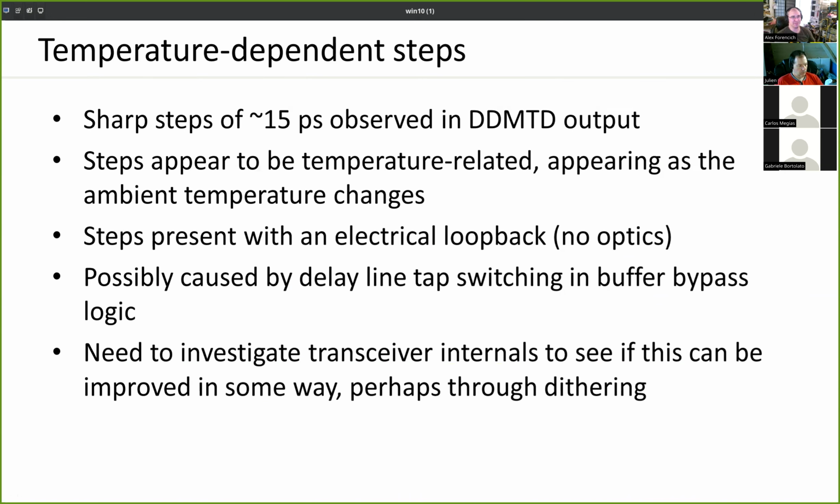I'm not sure how much I've discussed this previously, but inside of the GTs, the clock used on the FPGA logic side is provided by the FPGA fabric logic. It's not provided by the transceiver. The way the clock works is the transceiver has an output that drives the global clock network. Then it comes back and drives the TX/RX user clock inputs on the transceiver. This means that the internal transceiver X clock is not aligned with the TX/RX user clock coming in from the fabric. So for the delay alignment logic, I think they add a delay line on that output that feeds the fabric.